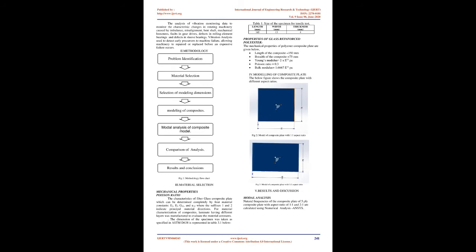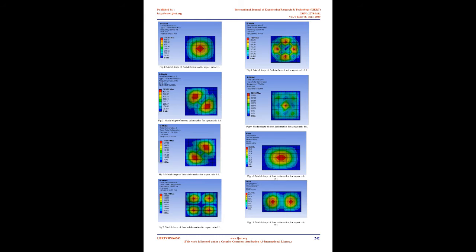Glass fiber reinforced with resin always possesses varying properties with the variation in the direction of ply, orientation of ply and number of ply. The different types of glass fibers used, based on their mixture of various materials, are as follows. A glass, soda lime silicate glasses, were used for higher strength, durability, and good electrical resistivity as compared to other glass fiber types. C glass, calcium borosilicate glasses, are used in highly corrosive environments because of their higher chemical stability. D glass, borosilicate glasses with a low dielectric constant, mainly finds applications in electrical fields.